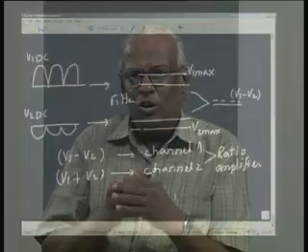They are filtered to get only the mean values, and these mean values are subtracted in one channel, added in the second channel, and the ratio is taken, and the ratio is now independent of the variations in the input voltage. That is the basic reason why we want to do this one. This is going to give you a signal which is going to vary with the delta P.